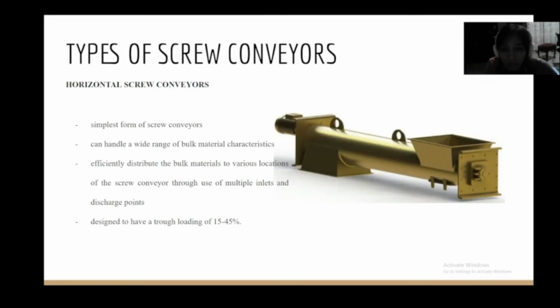Trough loading refers to the maximum depth at which the trough can be loaded to prevent undue wear and fatigue on the screw conveyor components. It depends on the characteristic of the bulk materials to be handled, and it is an important factor in screw conveying sizing. Generally, trough loading can be higher for light, free-flowing and non-abrasive materials and must be lower for viscous, heavy and abrasive materials.